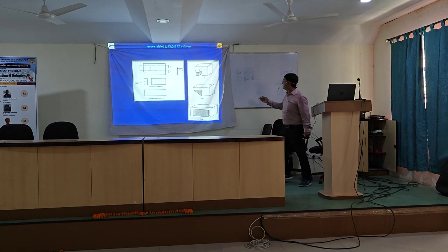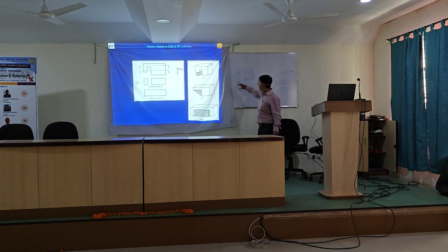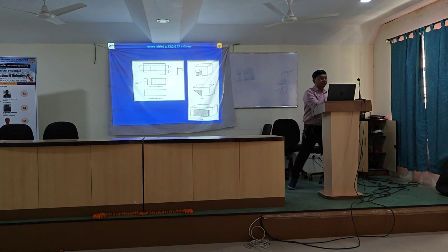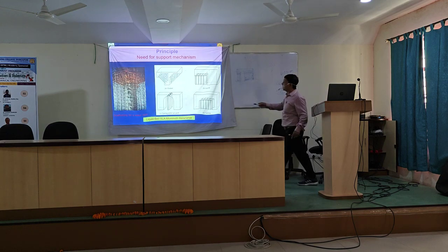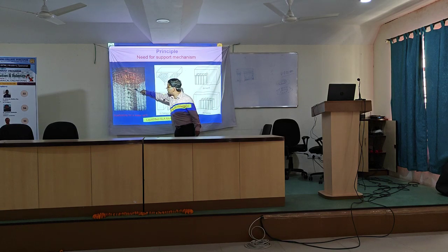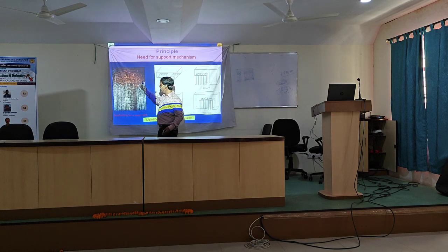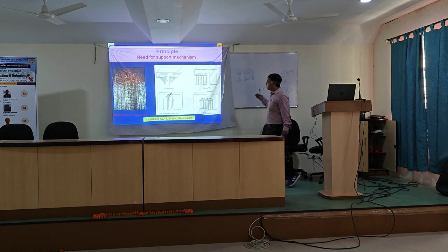with this orientation. Because below that there is liquid resin, what you have to do in the CAD model itself is create a geometry, that is the support structure. You have to create a geometry of relatively lighter shape so that from the bottom itself, this particular structure will cure and provide the support for this particular layer. This is called the support structure, which you might see in the case of a water tank in civil engineering. In the water tank, the central portion needs no support structure because it is built from the ground. But for the overhang portion, you need this type of support structure, as in civil engineering. The same concept is here also.